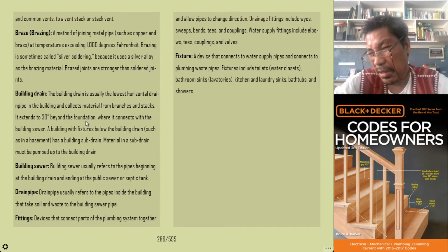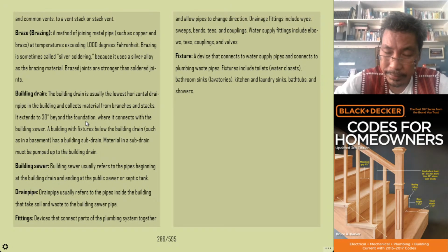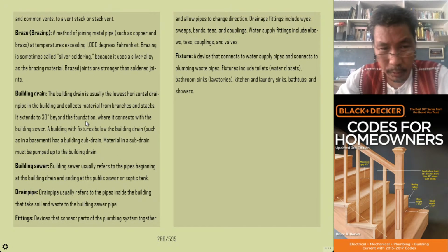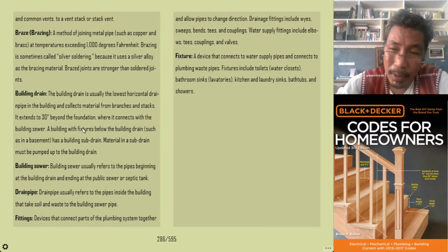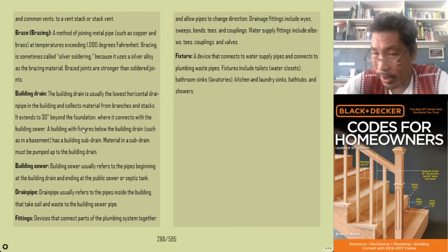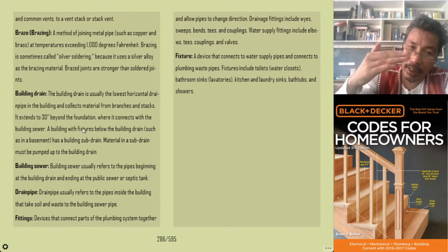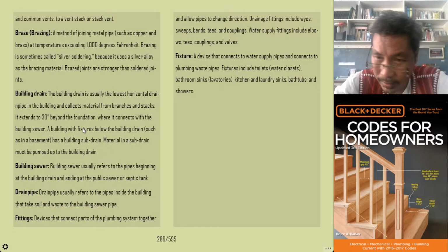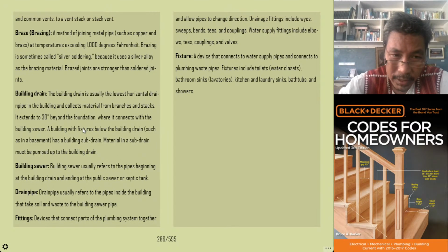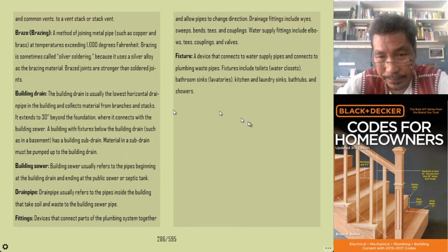So you have to put it under the soil, 30 inches beyond the foundation. So where is the foundation? What is the depth of the foundation? And then measure another 30 inches going down further beyond, and that is your location of the building drain.